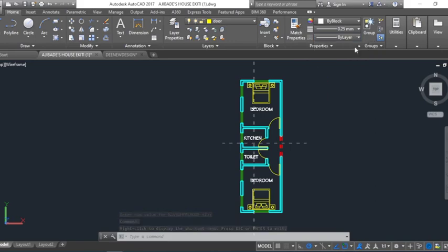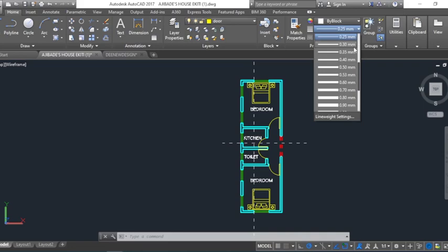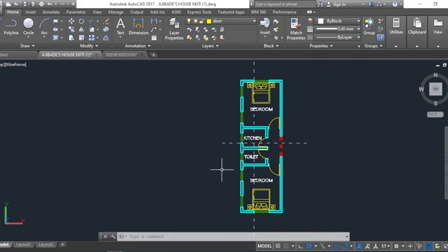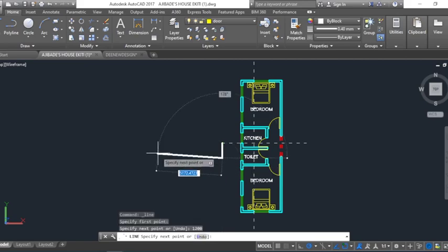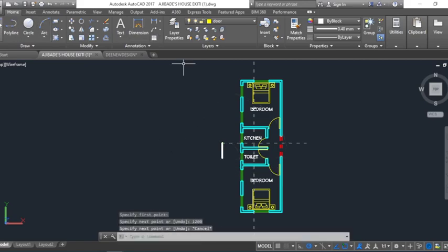we'll go back to layer. We'll set that there. Then we need a thicker line, something thick. Let me use 40. So I'll pick my line. Then I would just set highlight from here to, let me use 1 2, distance of 1 2. Then enter. Okay, escape. So pick my line again.